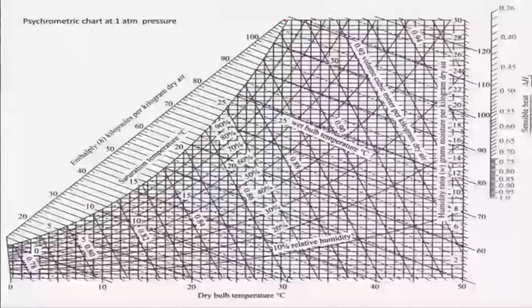If you want a different pressure, it will be different. For example, when you go to a higher altitude, the pressure will be lower, then you will have slightly different values. Now, if you recall, we had taken a dry bulb temperature, and we also looked at the wet bulb temperature as 30 degrees Celsius. We solved this problem by calculating and considering it as an adiabatic saturator, but here we can do it very easily, because we did a lot of calculation before.